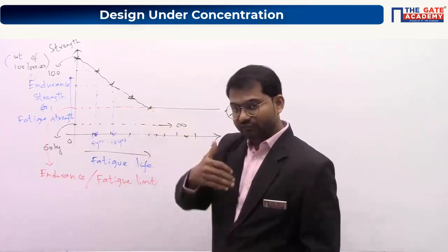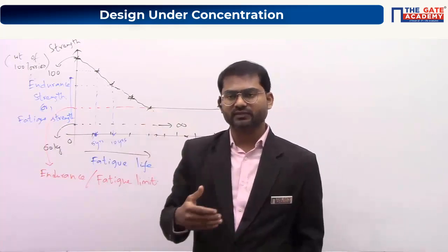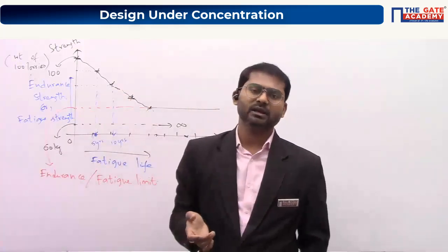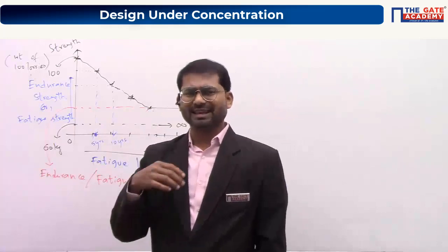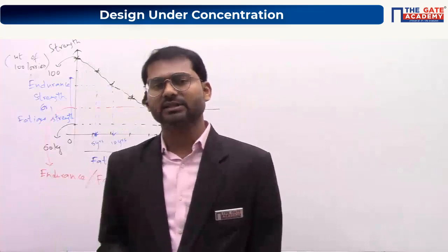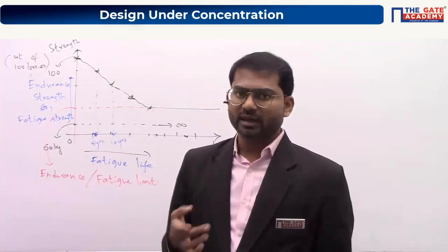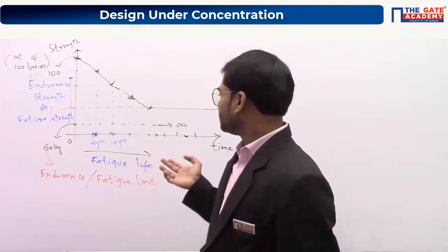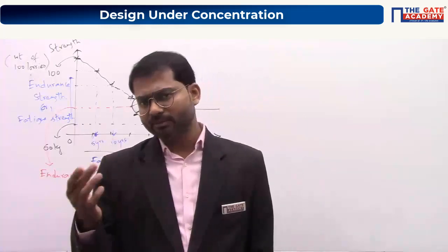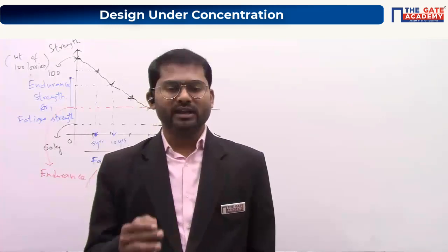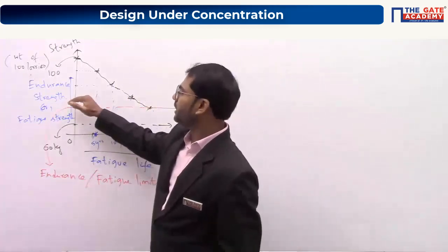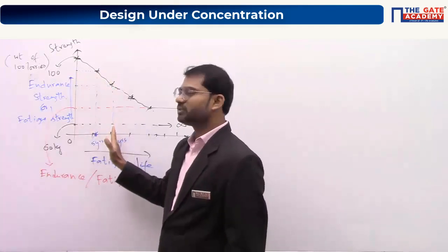Okay. So if you create a stress which is less than the endurance limit, then it can have infinite life. Regarding that, I'm talking here. Very rare cases are there where we apply a stress which is lesser than the endurance limit and achieve a situation of infinite life. In 99.9999% of cases, we have finite life cases only. That means we apply a stress which is more than the endurance limit, and there is a certain amount of time up to which we can use it.